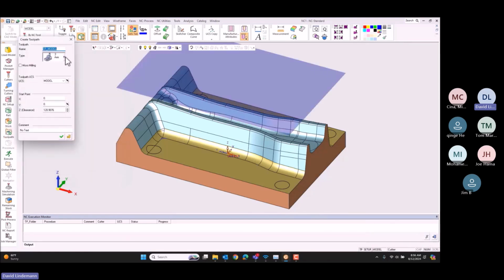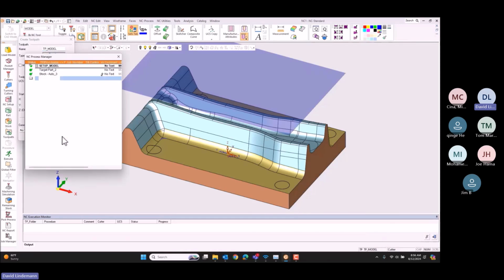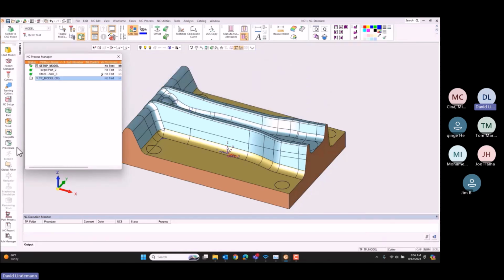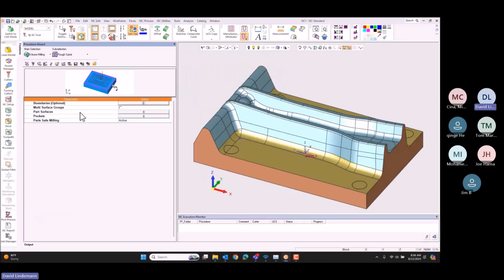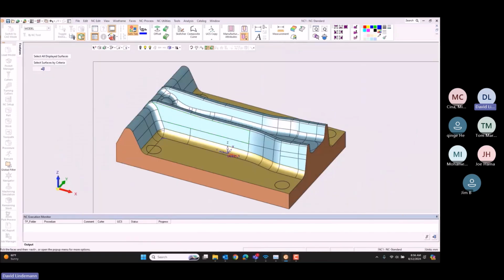The other thing was called the target. That's what am I going to cut to. Do I want to stick to 3-axis, go up to 5-axis? It's all there. It's just depending upon what my license has available for me. We'll do our first rough cut. You can see there's a huge library of different cutting styles that you can use, different types of tool paths.